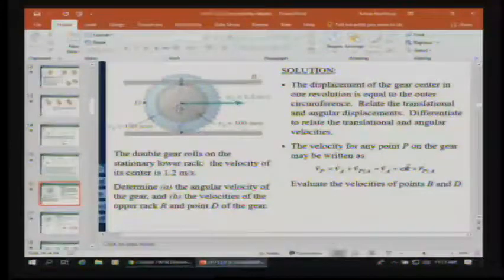So we're really not interested in the larger outside gear, but the relative motion is going to be, the R value, in other words, is going to be, if we're taking this as a center, from B to A, not to the outside, not to D. If we had something over there, we could talk about the motion of D as well.